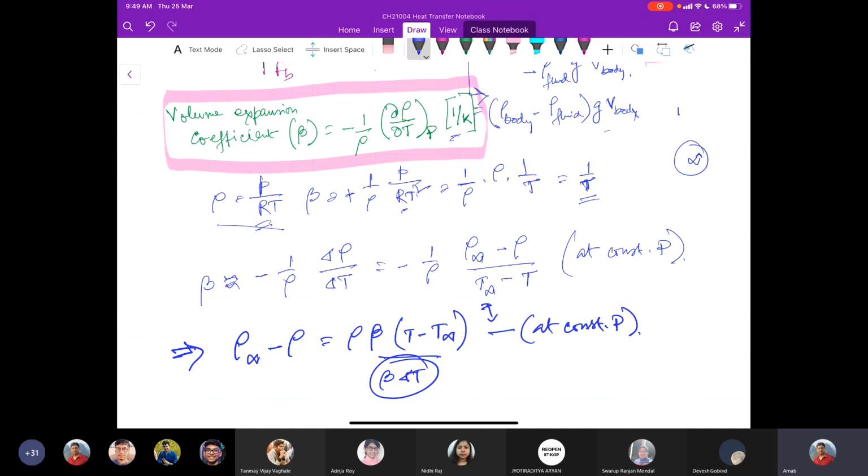So in order to increase the heat transfer rate, by now you are aware of the concept of fins, right? The concept of extended surface. Now, as you increase the extended surfaces, the fluid is moving over these extended surfaces. Now we are focusing on the natural convection part only. Remember, there is no external fan or no external blower.